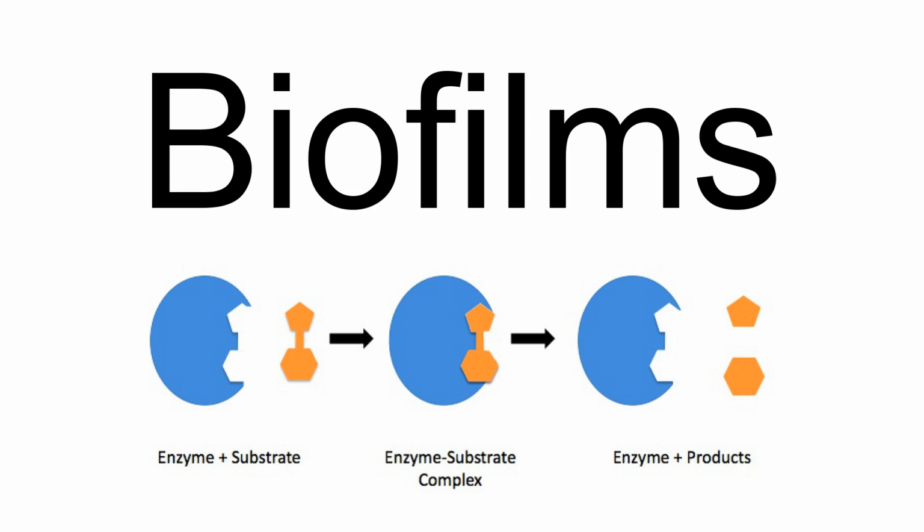These microorganisms then attach reversibly by van der Waals forces, followed by irreversible adhesion through self-produced attachment structures such as pili or flagella. Biofilms form on solid substrates such as stainless steel. A biofilm's enclosing polymeric matrix offers protection to its microbes, increasing their resistance to detergents and cleaning agents. Biofilms on food processing surfaces can be a biological hazard to food safety. Increased chemical resistance in biofilms can lead to a persistent contamination condition.